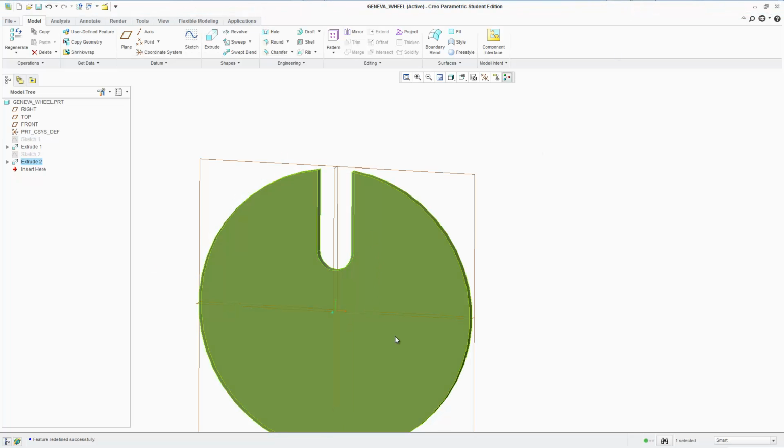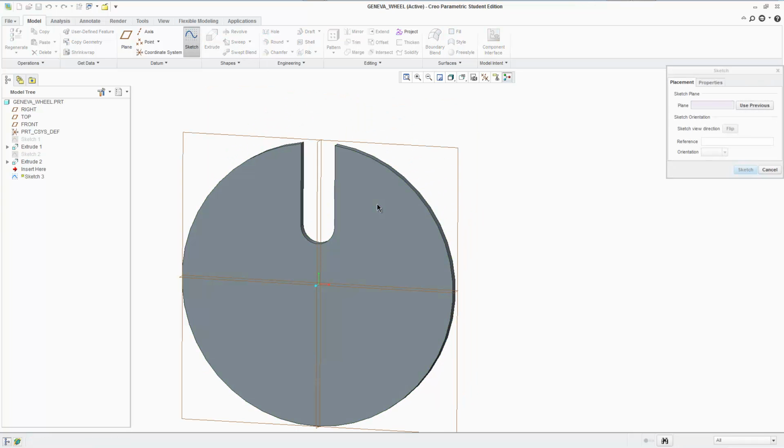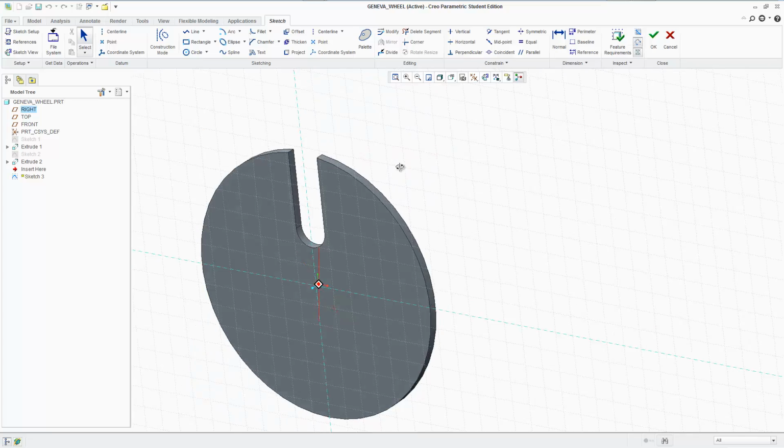And as I said, I want 4 slots. I don't know if I said that, but I want 4 slots. And we're going to sketch into this. If we're going to have 4 slots, they're going to be 90 degrees apart, right? One's going to be in horizontal both sides and vertical both sides. So, 1, 2, 3, 4. And same way for the disc stop radius, 1, 2, 3, 4. So I'm just going to make one here, and you probably already guessed what I'm going to do afterwards. I'm just going to pattern those cuts across, but we'll get to that.